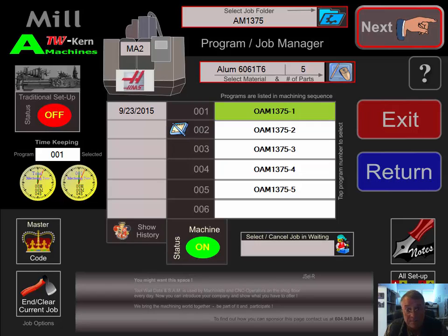our setup is complete. In this example, however, there were only 2 tools which were already in the machine, so we saved actually two tools that had to be reset up. In many cases, however, there are many more tools. For instance, half of the tools, or even more, could be already in the machine, but not in the correct position.